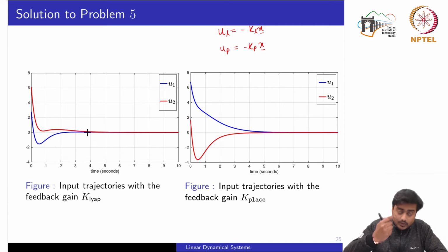If you want to compute the control energy, you can compute it by using the formulas introduced in the earlier weeks. But by using the place command, we are getting higher energy, or at least as it appears in the signal U2. While here the U1 trajectory is more subtle than the U1 trajectory for the first feedback loop.